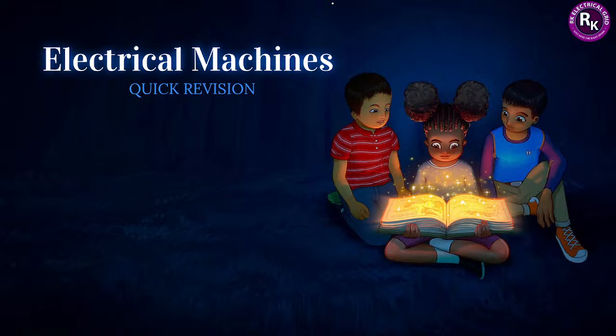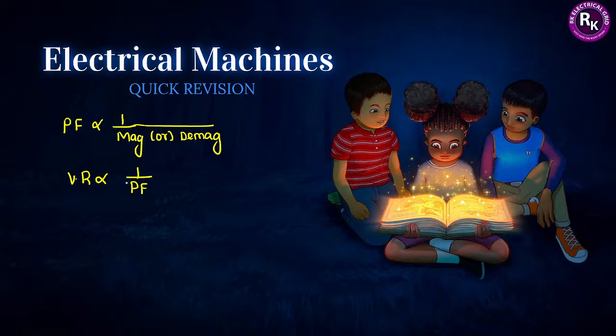What quick revision I had given: the relation between power factor and magnetization effect. We saw that the magnetization effect and the demagnetization effect are both inversely proportional to power factor. And I also told you that voltage regulation will also be inversely proportional to the value of power factor. So these things we concluded in the last class.